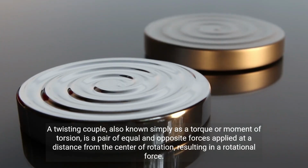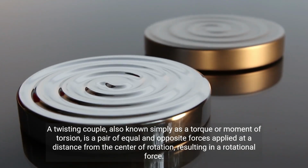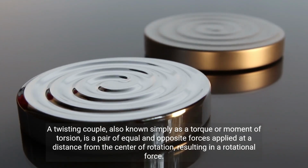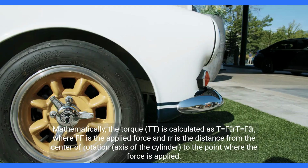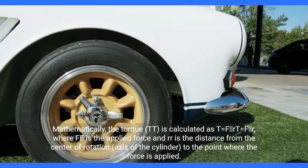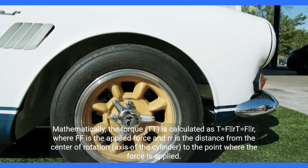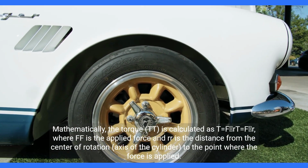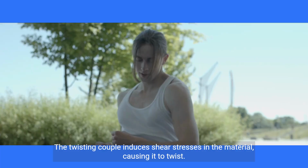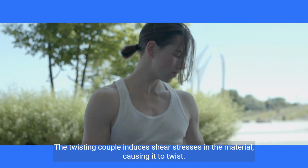A twisting couple, also known simply as a torque or moment of torsion, is a pair of equal and opposite forces applied at a distance from the center of rotation, resulting in a rotational force. Mathematically, the torque, T, is calculated as T = FR, where F is the applied force and R is the distance from the center of rotation, the axis of the cylinder, to the point where the force is applied. The twisting couple induces shear stresses in the material, causing it to twist.